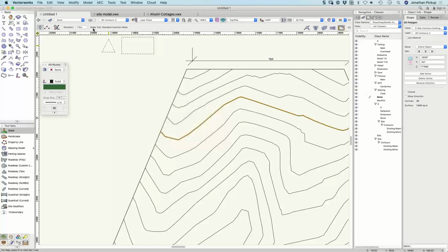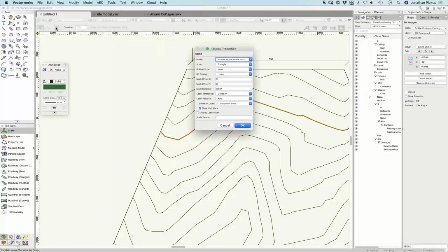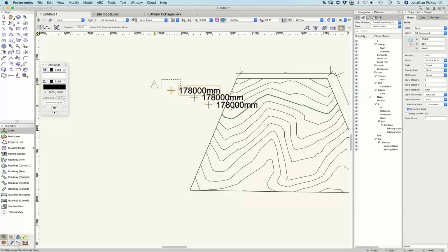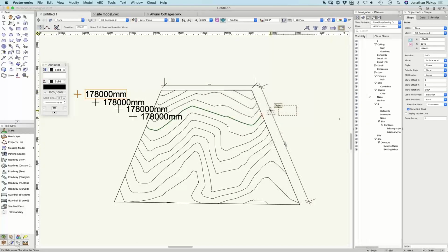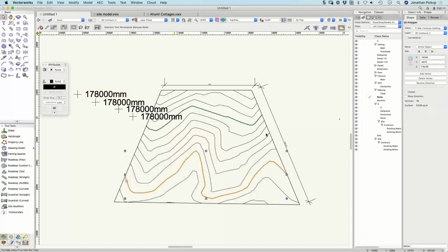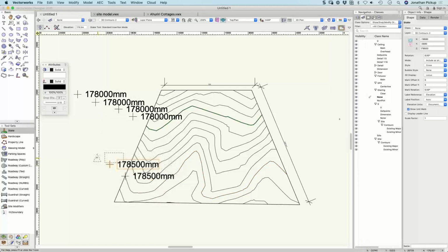So we think the contours carry on out here. We've got some council and some Google Maps, and it shows the contours carrying on, but the survey didn't go out that far. So we know we've got some contours out there. And we also think that some go this way as well. I'll leave one side alone. What about this one here? What elevation's that? It's 178.5. So back to my stake object, 178.5 m.